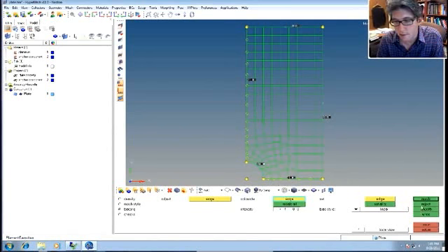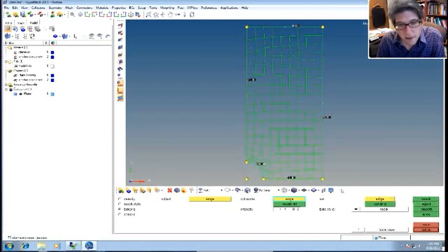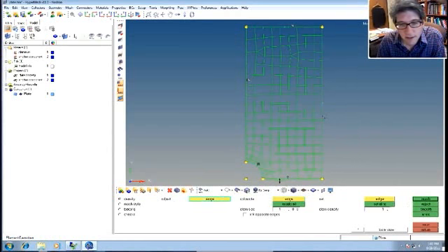So now we can do a reject, and now if we mesh again, you can see it starts to get a little better because we've added more nodes here. Now, probably what I should do is go back to the density and put in some more nodes on this side. So let's set this to 10. Add a couple more in there.